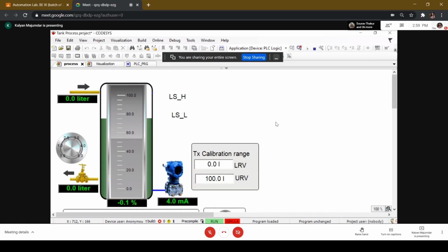Now we are gradually moving into how to develop this model. First of all, we are developing a model that will be tested. This model will be interfaced with the controller that you're developing in version 1. Since we are in the simulation, we want experiment results to be out quickly. We don't want this one tank to take 1 hour to fill up, because then we'll have to wait 1 hour to see whether your controller is working or not. So a typical time should be something around 7, 10, or 15 seconds for this particular tank to fill up, so that you can do your experiments fast.